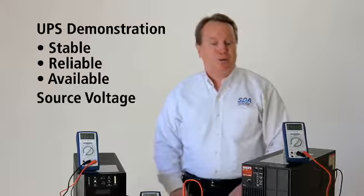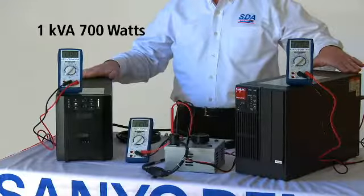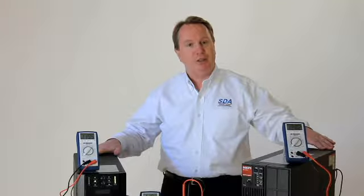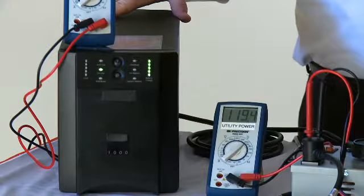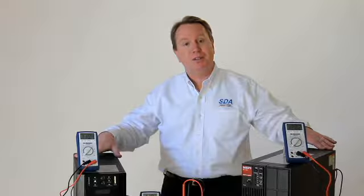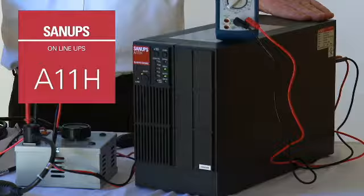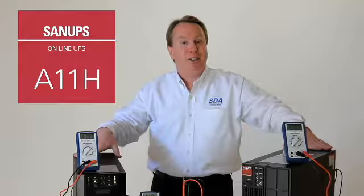Let's describe our equipment. Today we have two conventional tower UPSs, both of the same power, 1 kVA, 700 watts. Two different topologies. This unit is an industry standard. It's probably one of the most popular UPSs on the market today within the line interactive category. On my left, we have the Sanyo Denki America, SANUPS, A11H, or known as SANUPS A. This is a true online double conversion UPS.